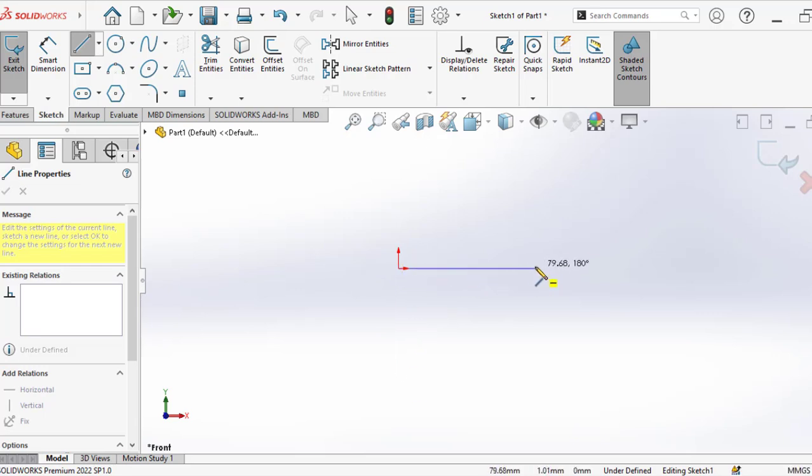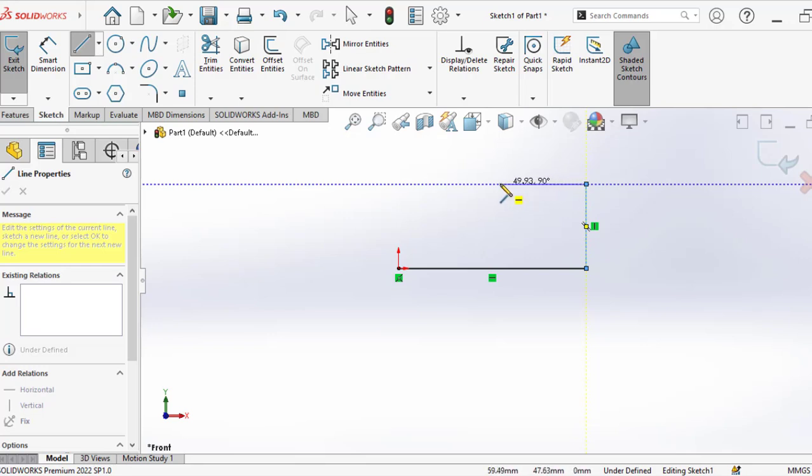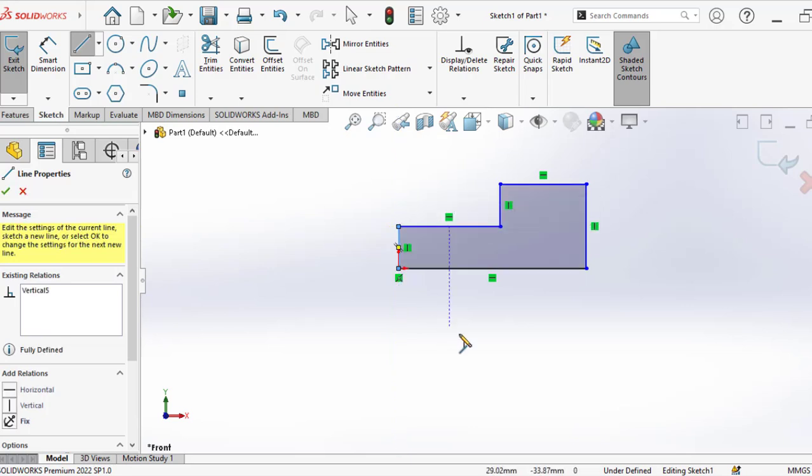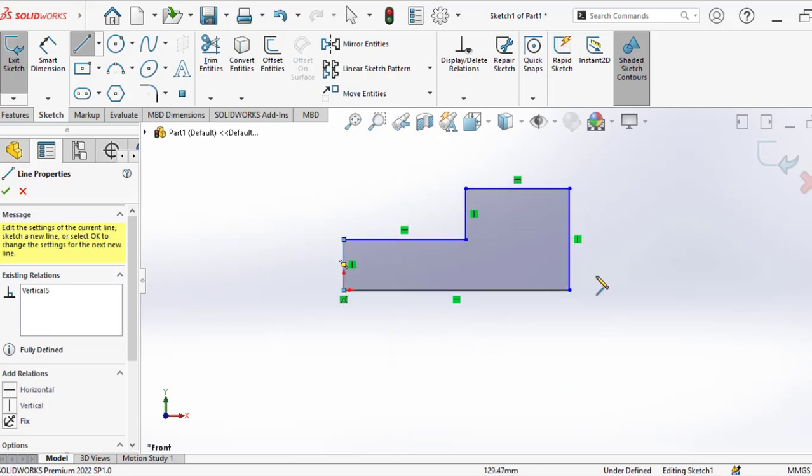Now you click the next point, because a line has to have two points. Again the line will appear and you can go in any direction and make a single click. This will create line segments. Each segment is a single line segment. If the line segments are completely closed, then it is a closed loop.